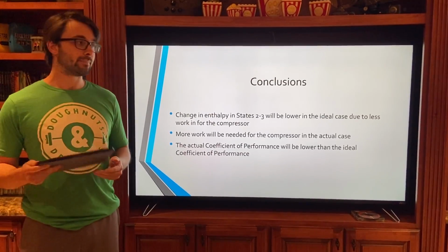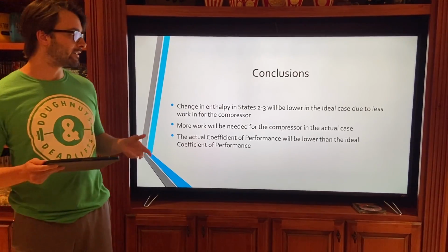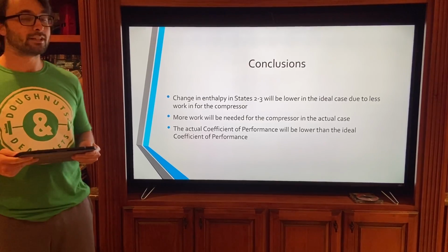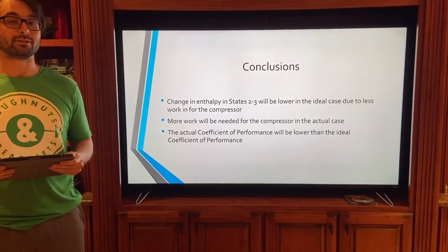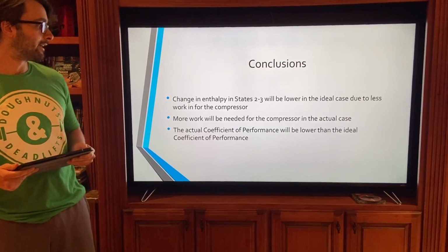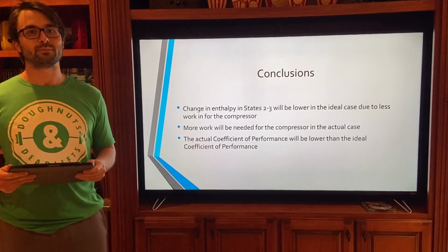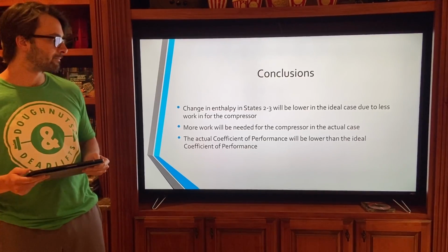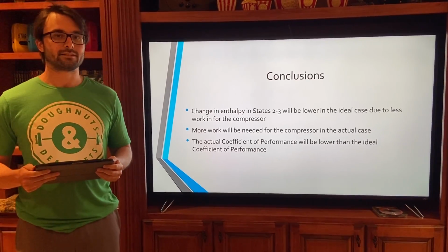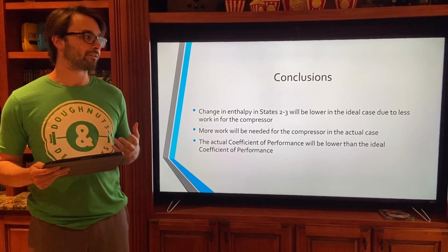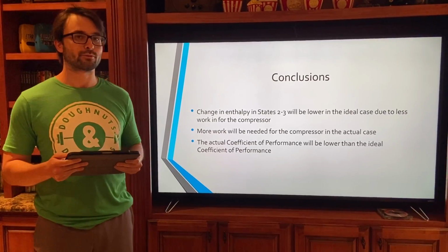Some conclusions that were made are that the change in enthalpy from states 2 to 3 will be lower in the ideal case due to less work needed for the input in the compressor, and more work will be needed as input in the actual case in the compressor. And in the actual case, the actual coefficient of performance will be lower than the ideal coefficient of performance.